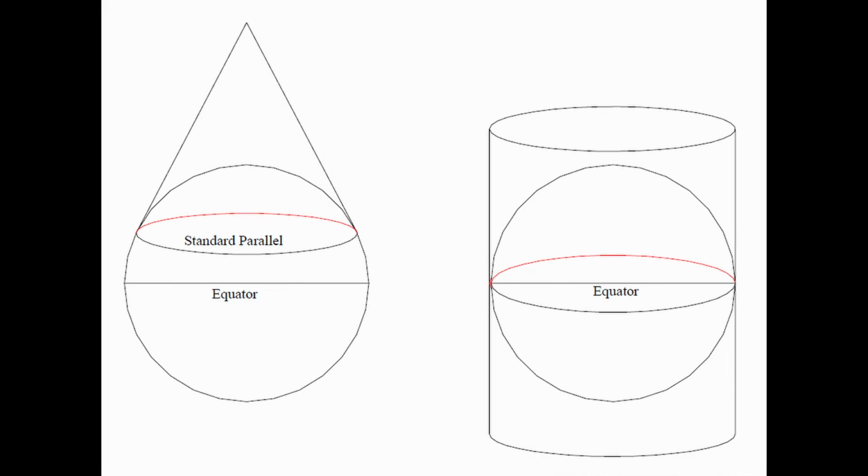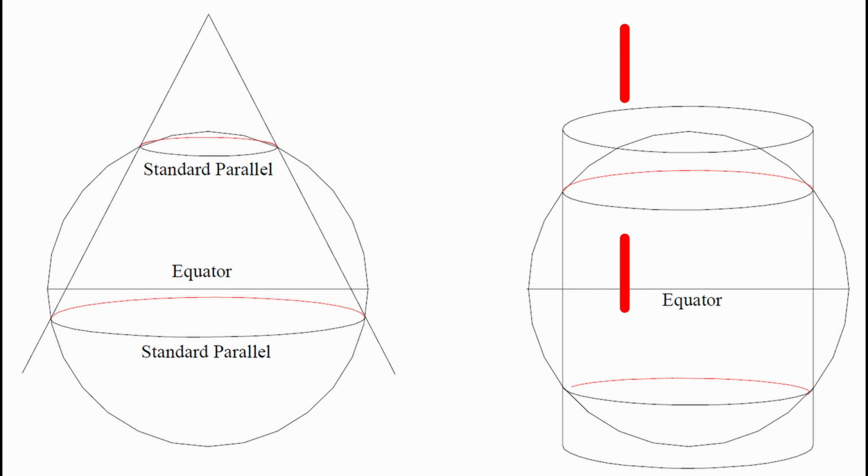Another method that is used to reduce mapping projection distortion, which UTM also uses, is that instead of the developable shape only touching the ellipsoid along a single line, also known as a tangential projection, the developable shape cuts through the ellipsoid, which creates 2 lines of zero distortion. This is referred to as a secant projection. This again reduces the relative distance and therefore the distortion of a point to one of these intersection lines.